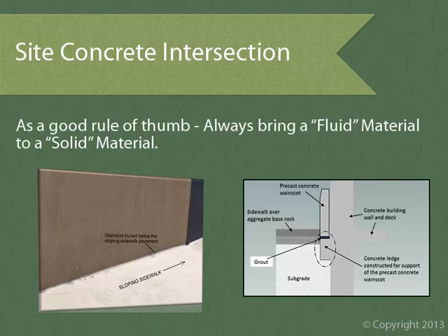Taking into account construction tolerances and the fact that the wainscot will be fabricated in the shop, if the sidewalk were to run below the wainscot, it would inevitably result in an uneven gap from the bottom of precast to the top of sidewalk. This general rule is applicable for just about any fluid to solid system interfaces, including facade interfaces involving plaster. This same principle would apply at, say, a plaster soffit or wall where it meets precast, metal panels, or any other solid product.